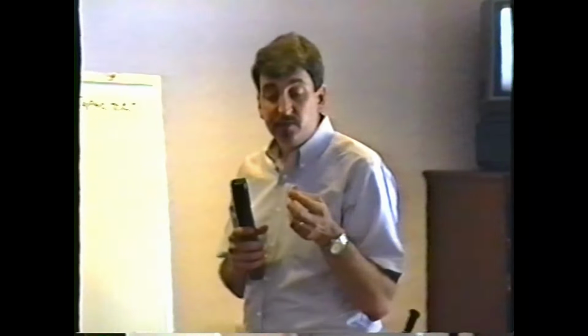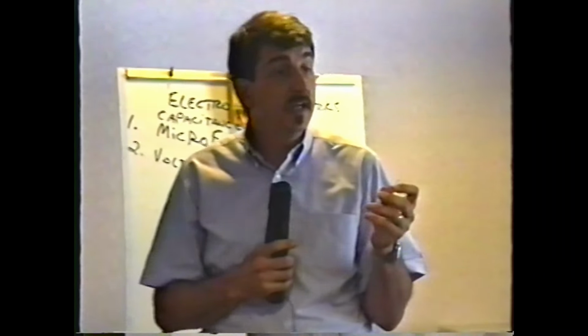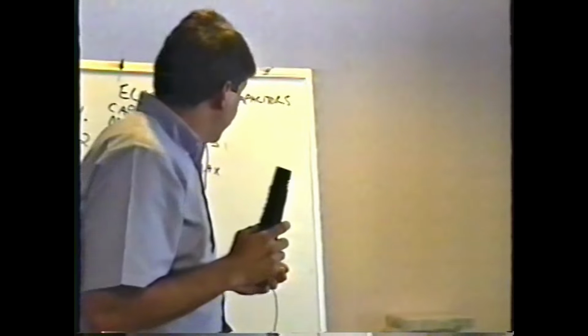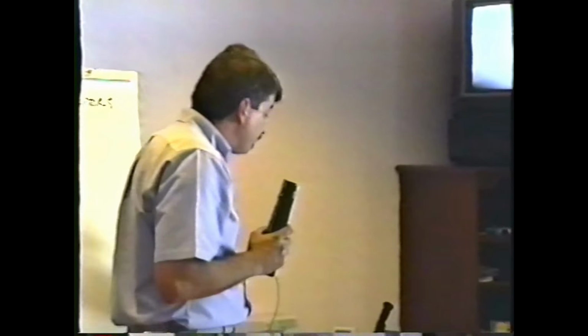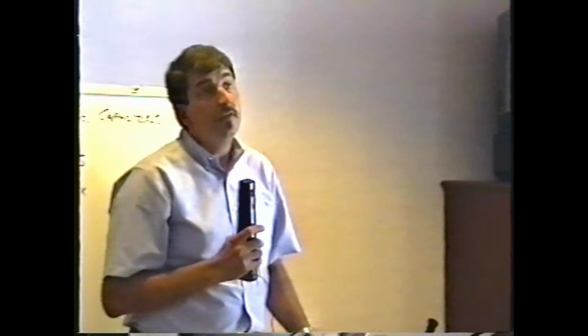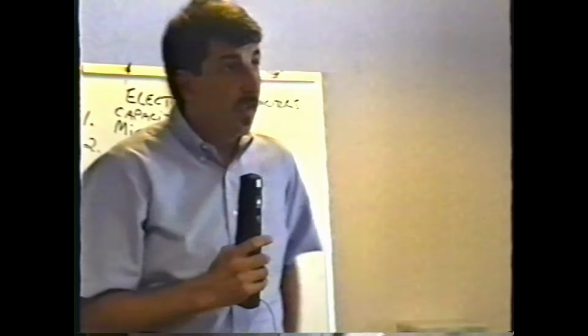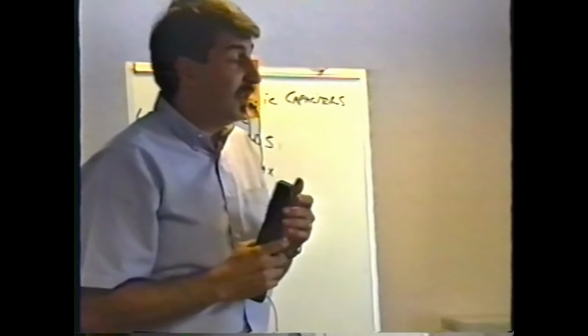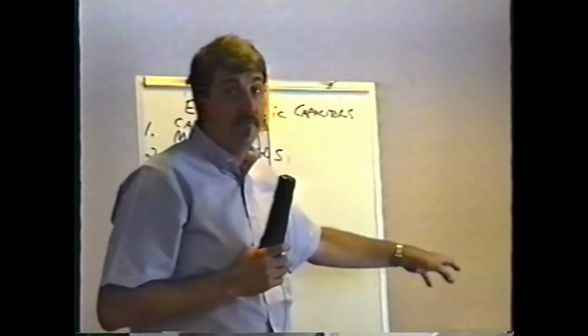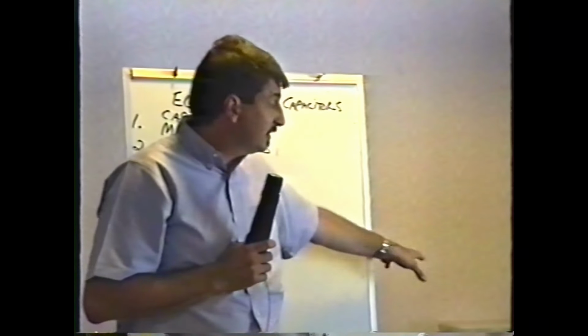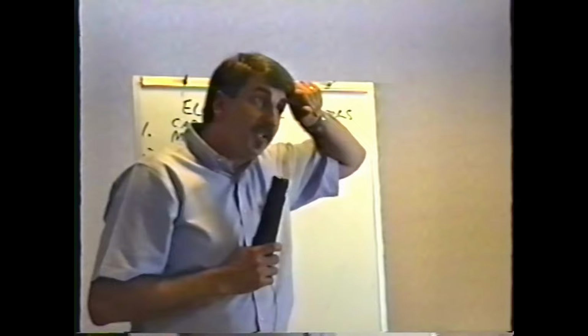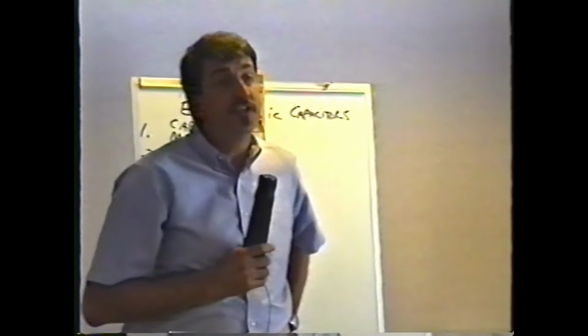It just charges faster. So you need to be able to tell exactly how many microfarads it is. And so I strongly suggest that if you're going to do a lot of monitor repair, you get a capacitor meter. Now, you don't have to have one. In fact, I've only had one for the past few years, and I've repaired lots of monitors before I had a capacitor meter. But the only other way to check it out is by substitution.